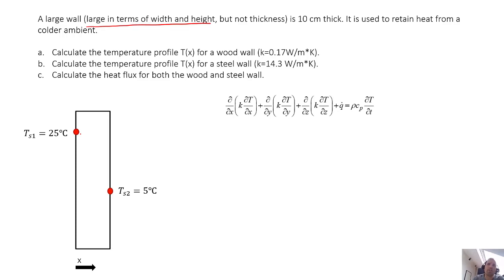When we've solved energy balances previously, we've solved these kind of macro level energy balances, and we're assuming that our entire solid is all at a uniform temperature, and we're just trying to figure out what is that temperature. Well, now instead of just this simple algebraic energy balance, we have this differential equation as our energy balance. And what we're going to get as we solve this differential equation is not a single temperature, but rather a temperature profile, or an equation that tells us how temperature changes in terms of space and time.